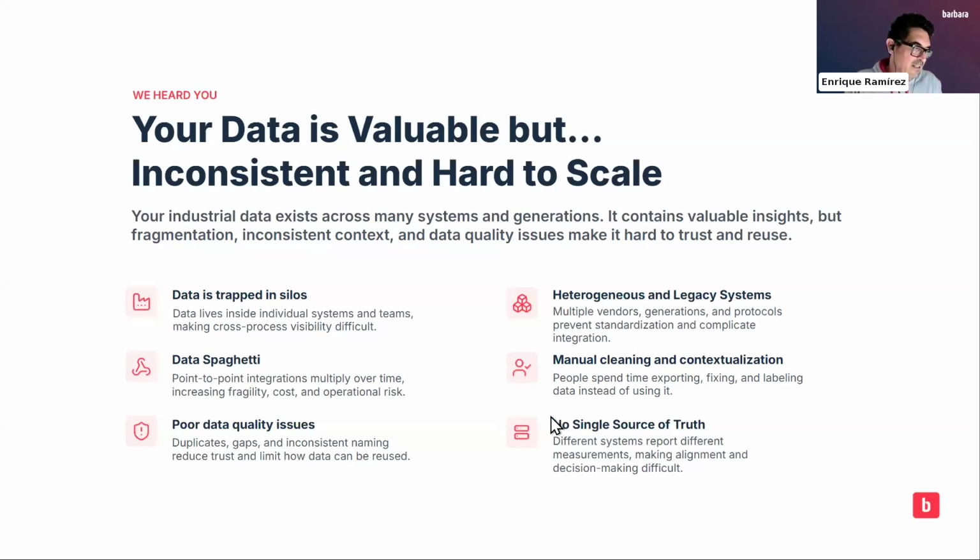Okay, and finally, and this is one of the targets that UNS has, is having a single source of truth. It's common, when you don't have the UNS, that you get the data from one sensor and send it to a system, then you have a second system connected to the first one that reads all the data and puts it there also. So in the end you have different databases with the same information here and here, so you don't have a single source of truth. That is something that we need to avoid using UNS.